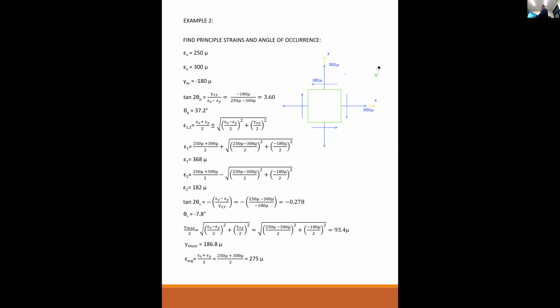And then, of course, the next thing we're going to do is use our Mohr circle. Same principle for Mohr circle. We can do it for strain or for stress, so really the same procedure. We're going to plot the center of the circle on the epsilon axis. That's not the sigma axis, there's a typo right there; that's supposed to be epsilon.